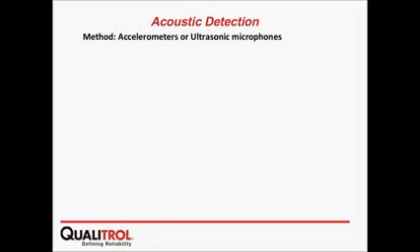So, acoustic detection. The method: accelerometers and ultrasonic microphones. So it will detect the acoustic waves. Its sensitivity is particularly good for particles. But as I mentioned before, for voids in the insulator, the attenuation is too high and it is not able to capture.